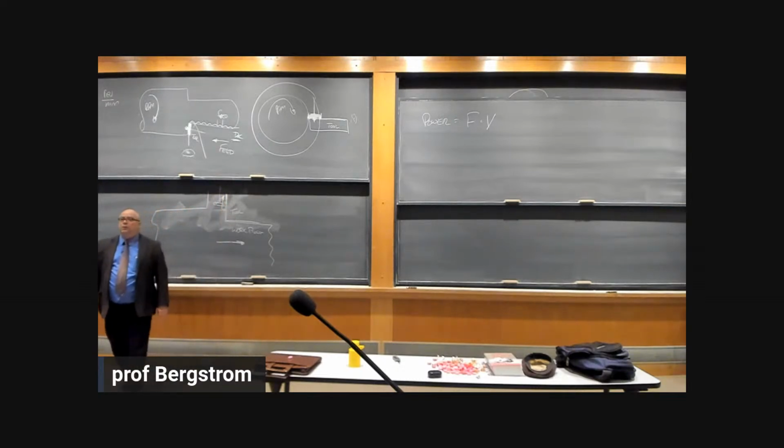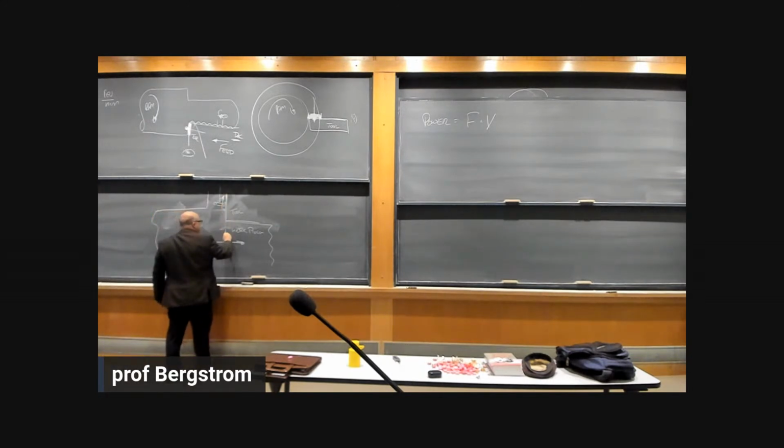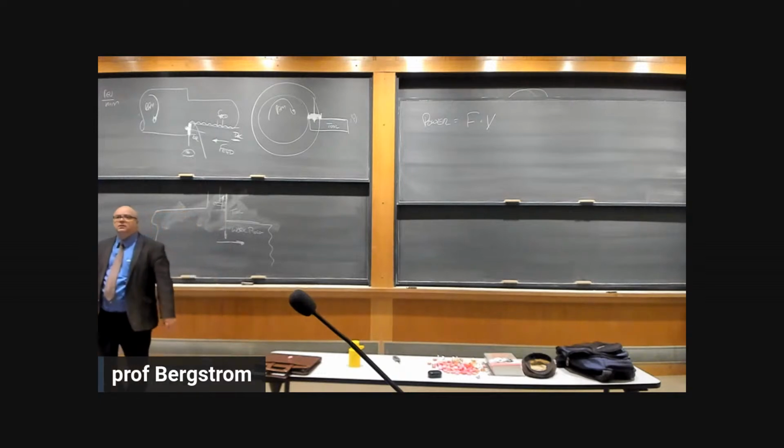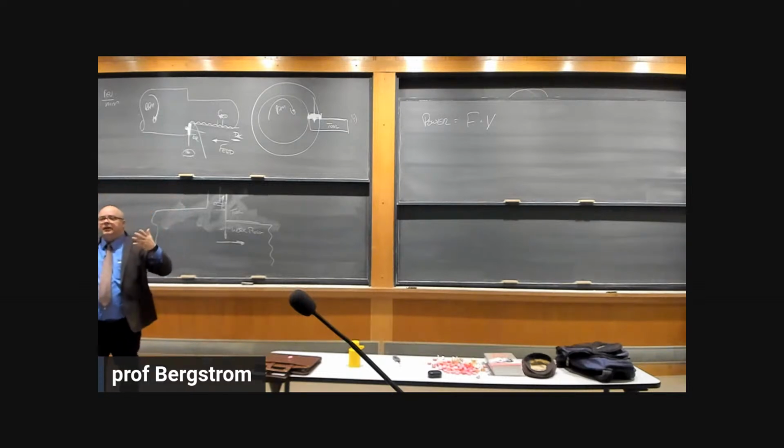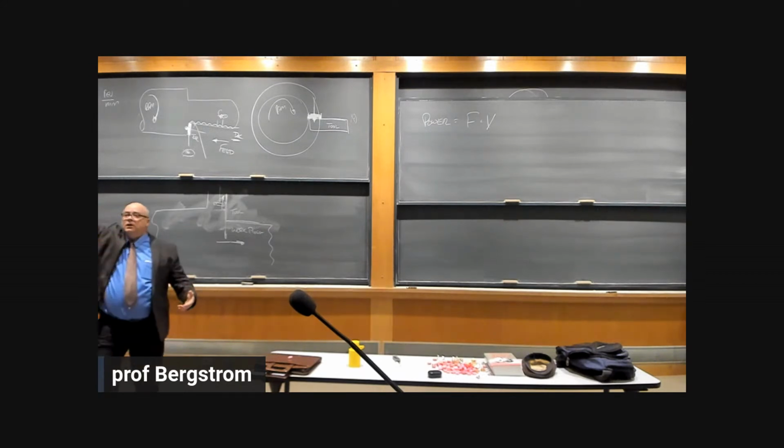Which means if it's moving this direction and it's pressing this direction, there's got to be a frictional force, right? Has to be. And so the frictional force is going to be opposite the direction of motion, pushing on the tool in the down direction. Which means something in the machine tool has to want to push the tool in the other direction, right? So that'll be the combination of the X and the Z servo motors that are pushing the tool back the other direction. Because we said steady state, we said no acceleration.